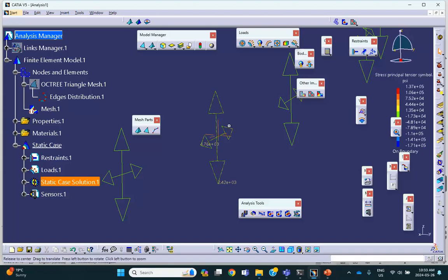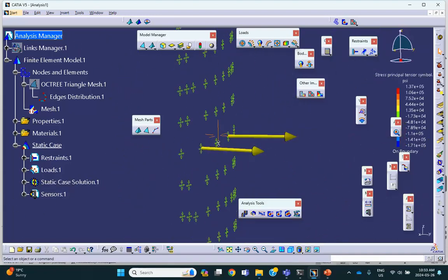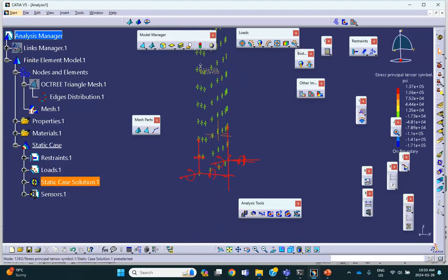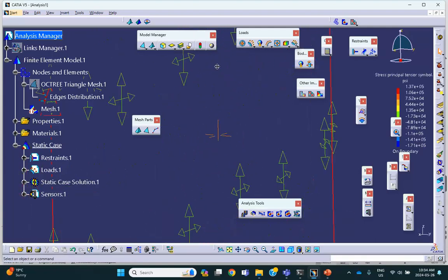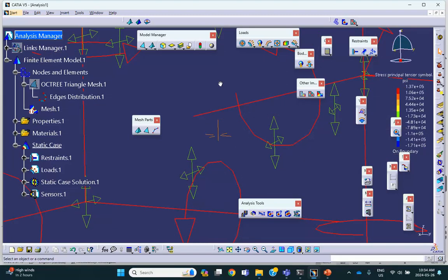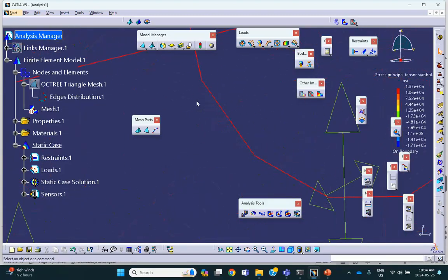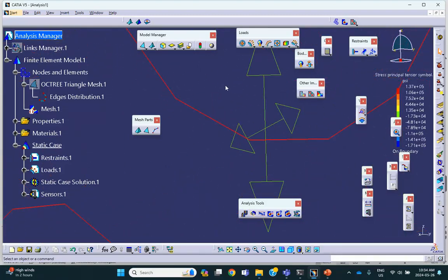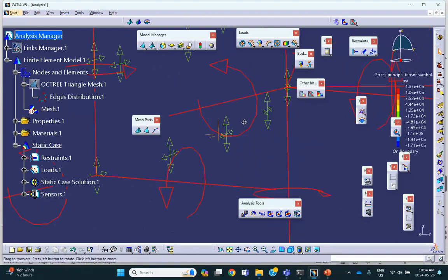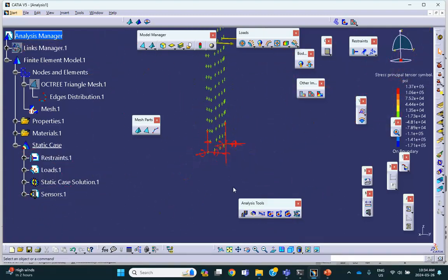Now, let's go back here. In fact, if you go further down here, the results are even going to be closer, because there we may have been too close to the top. Let's see now. Just watch these. These are close to the bottom. This should be closer to 2,500. Sorry, this is the hoop. This one says 2,360. And this one should be close to 5,000. It's 4,900. Yeah, and if you choose a finer mesh, my mesh is kind of big here, but that's okay.